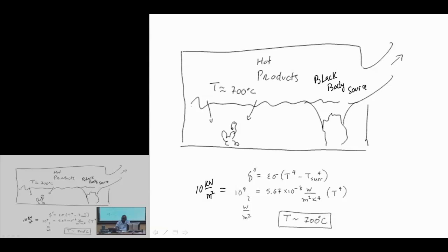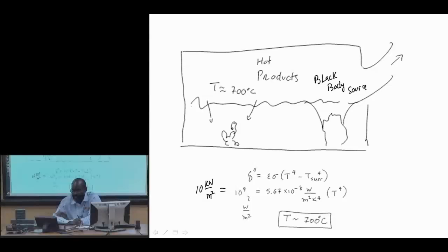Well, the mean absorption coefficient for the soot is much larger than for the gases, whether it's H2O, CO2, or CO, and the system becomes optically thick on length scales on the order of 1 meter. So if you're thinking about a 2.8 or 3 meter high room, then once you get 1 meter of filling, you're optically thick in terms of the radiation.